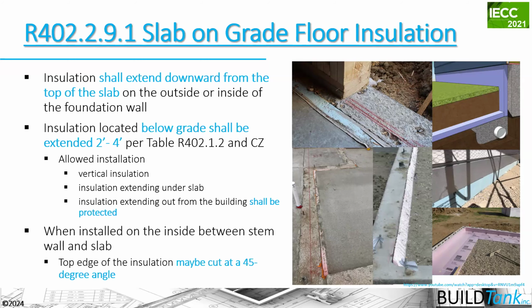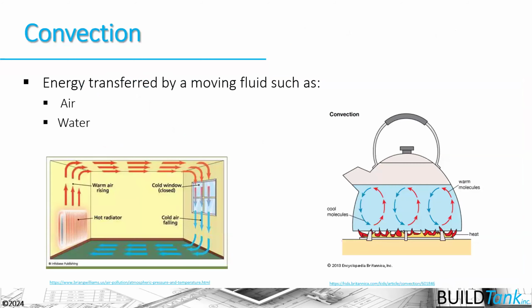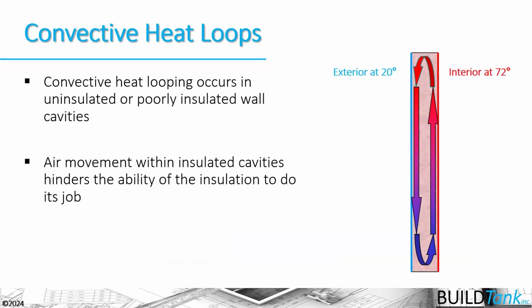Now, the other way that energy moves from inside to outside our houses is energy that's moving with air. It's energy that's transferred by a fluid, and that fluid can be air, it could be water as well, but from a house perspective, generally we're talking about energy that's moving with air, and that energy that's moving with air can cause the insulated cavity to malfunction or not work as well as it was intended.